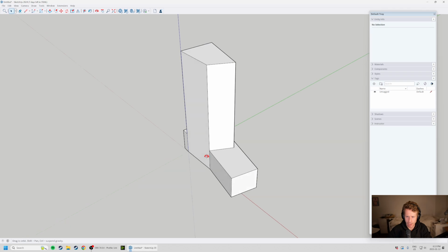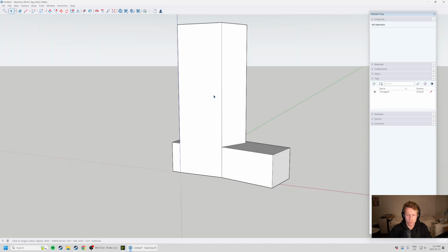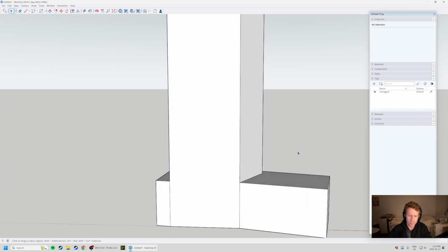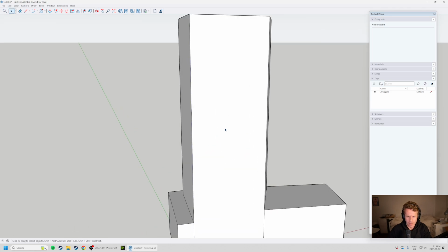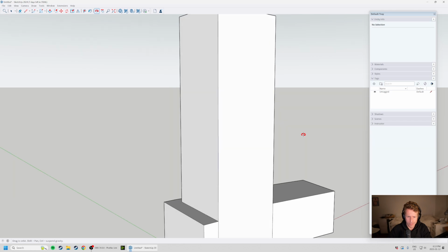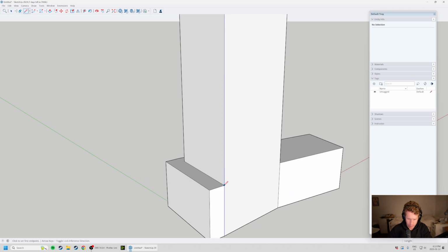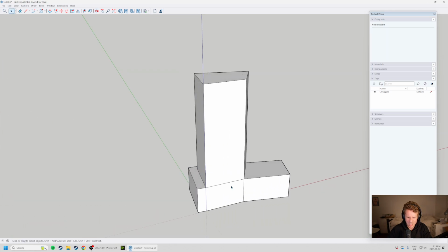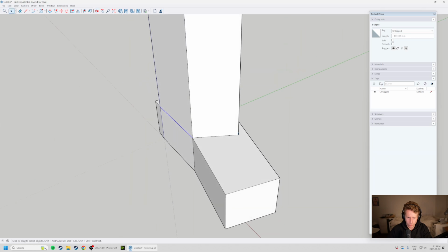But yeah, some fun stuff happening inside of SketchUp. So let's say we wanted to create a kind of hole at the midpoint of this building. The push-pull tool can also help us create holes in the building, if that makes sense. Right now, if I wanted to carve a hole into this building, it's hard, so I'm just going to eyeball something. But what we could do is draw from here to here. And let's say I wanted to see, objectively, where my floors were going to approximately be.